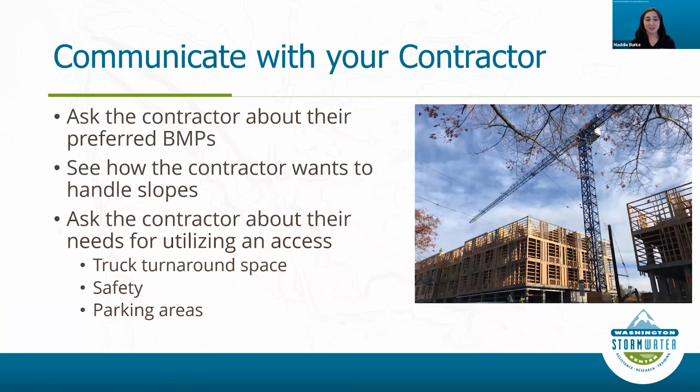So next, you need to communicate with your contractor. Your contractor has experience doing erosion and sediment control. Ask them about what their preferred BMPs are, if they have any idea about challenges that you might face on the site. See how your contractor wants to handle slopes, and also ask them about needs for utilizing their access. What's really common in the city of Vancouver is we only allow one construction access, but it might prove to have a safety issue or not have sufficient truck turnaround space. And in that case, we do allow exceptions. So that's something you want to talk to your contractor about.